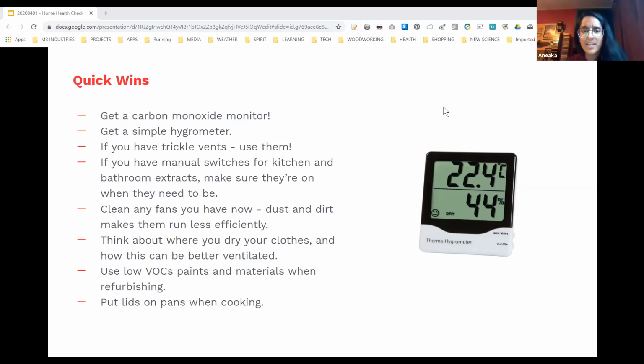I think certainly in any living environment, you're going to need to think about ventilation. Obviously, you wouldn't consider something like passive stack because that requires some height for the chimney effect of the passive stack to work. So that wouldn't be a system that would work for you, but certainly you'll have to think about what the appropriate ventilation is for you. I don't know if there's something else you meant by that question.